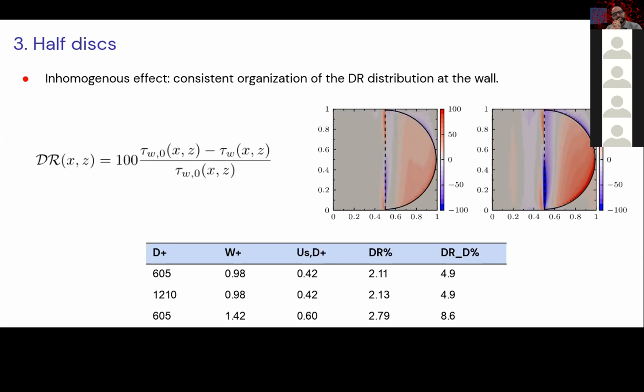This is the slip velocity we obtain on the disk surface, and introducing slip velocity at the wall is a well-known drag reduction paradigm that here we are trying to achieve through these passive devices. There are many other methods proposed in the literature to achieve slip velocity, among which hydrophobic surfaces, which are obviously a more complex technique.